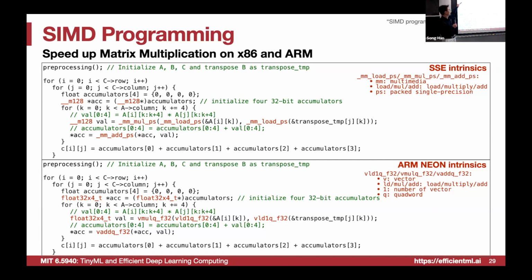As you can see, we have 4 loops. This is the same as before, but each operand is no longer a single number. There are 4 entries, so the register is 128 bits. Why 128? Because each number is 32 bits, and we have 4 of them at the same time. So every time the register is of width 128.